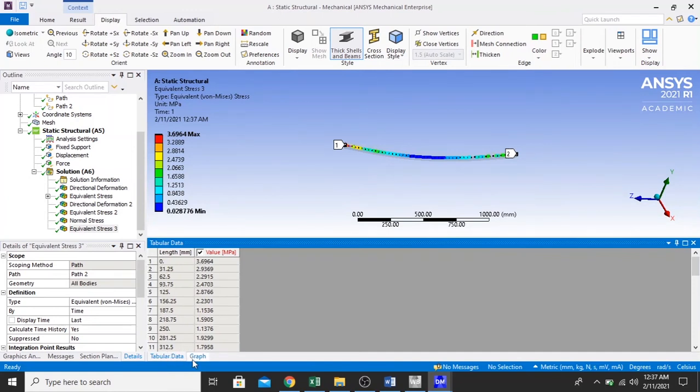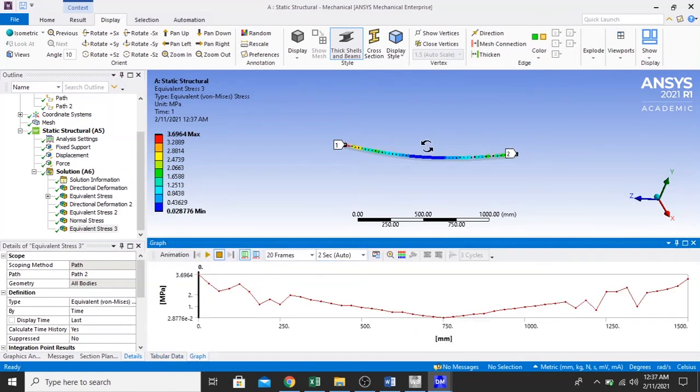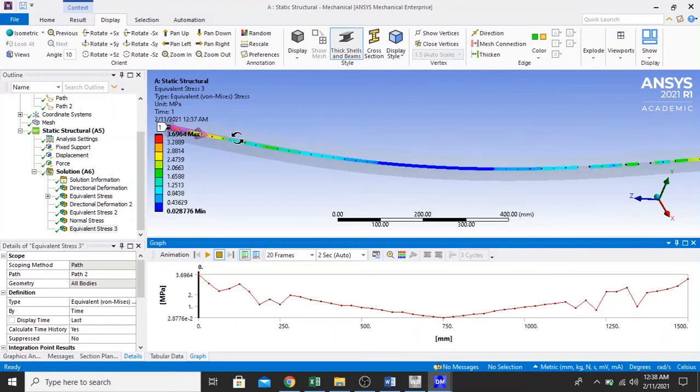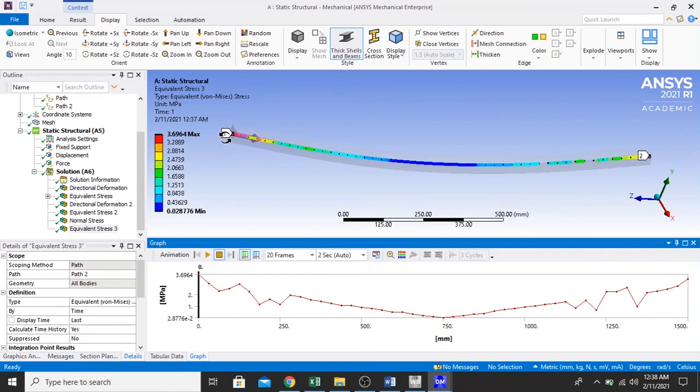In the top surface of the model, the graph is reversed compared with the graph in the middle position. The color of the equivalent stress in the middle is totally blue, which indicates that there is the lowest value of the equivalent stress, and there is a little bit of tension in the support right there.